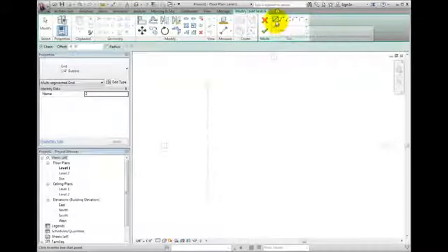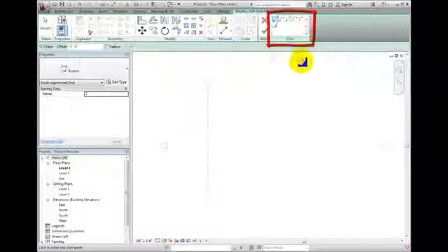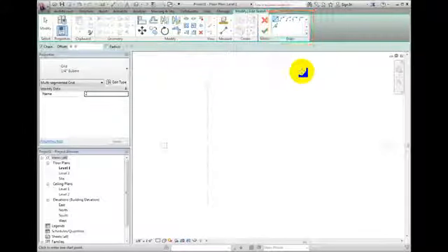We are now in Edit Sketch mode, and the Modify Edit Sketch contextual ribbon appears with multiple draw tools. You can now create a grid line with any series of straight and arc segments since multi-segment grid lines are sketched. In the options bar, notice that chain is selected by default because all the lines need to be connecting, but cannot form a closed loop.